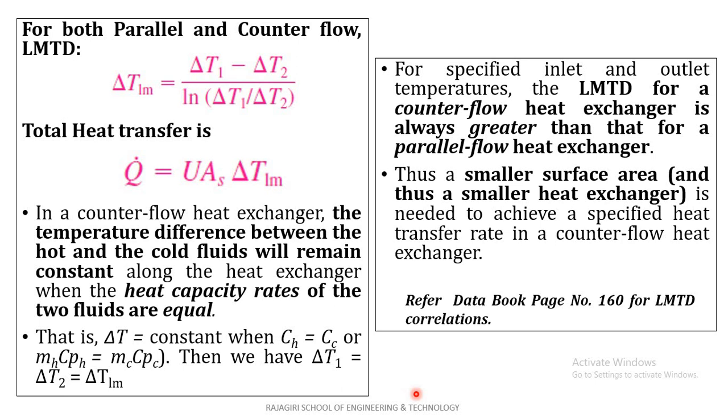Okay, so in a counterflow heat exchanger, the temperature difference between the hot and cold fluid will remain constant along the heat exchanger when the heat capacity rates, that is the m Cp values of both fluids, are equal. See here, if mh Cph is equal to mc Cpc, then in that case delta T1 is equal to delta T2.